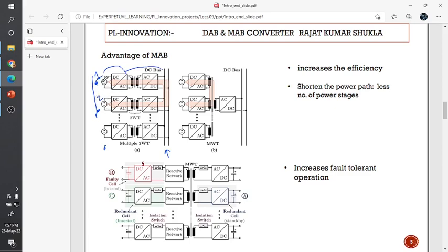So to transfer from position 1 to position 2, the secondary side, the DC to AC to DC converter, the secondary side H-bridges are extra and are being added. So the losses increase because switching losses and conduction losses are involved, right? So I don't want to transfer it. So here